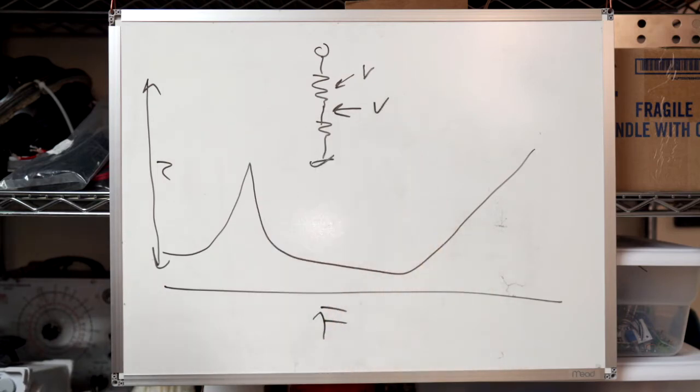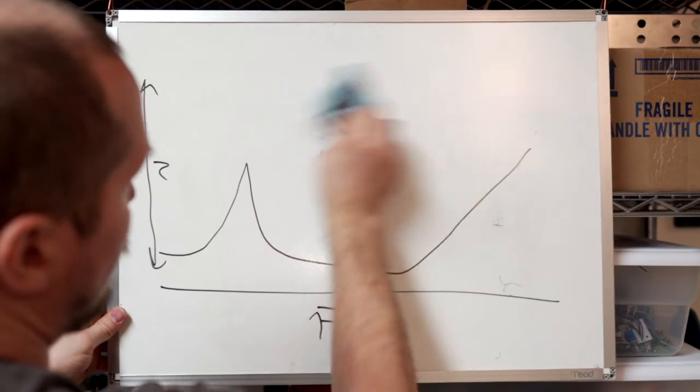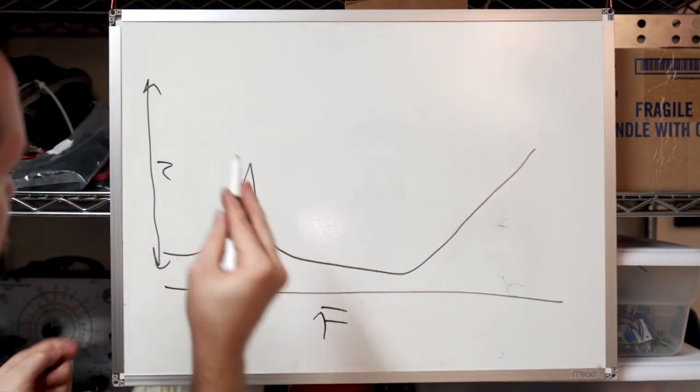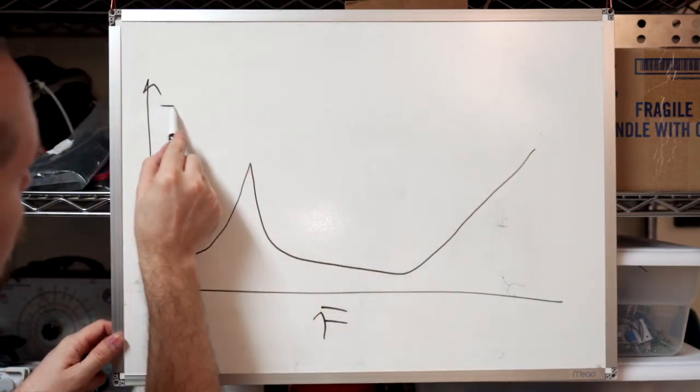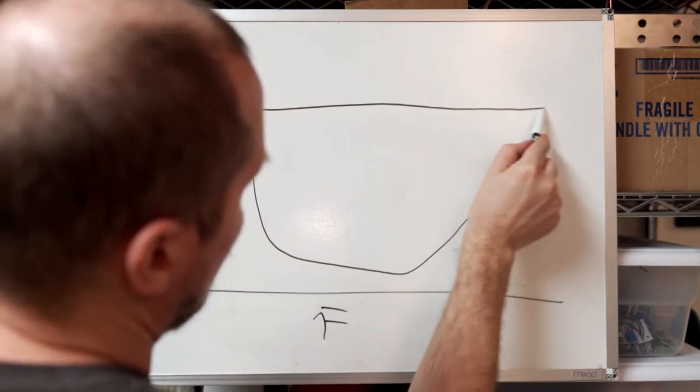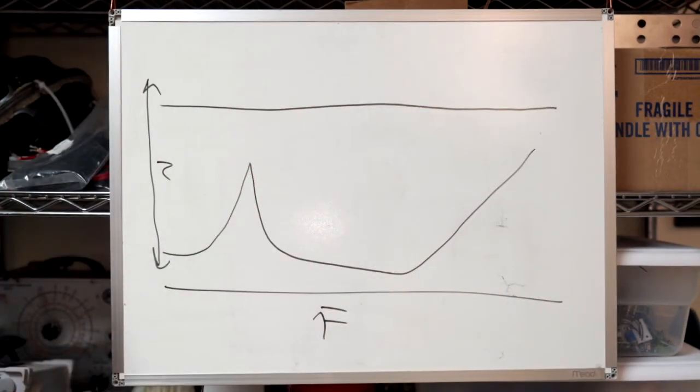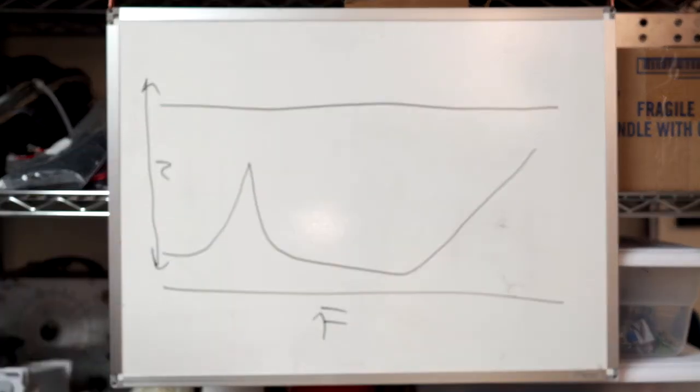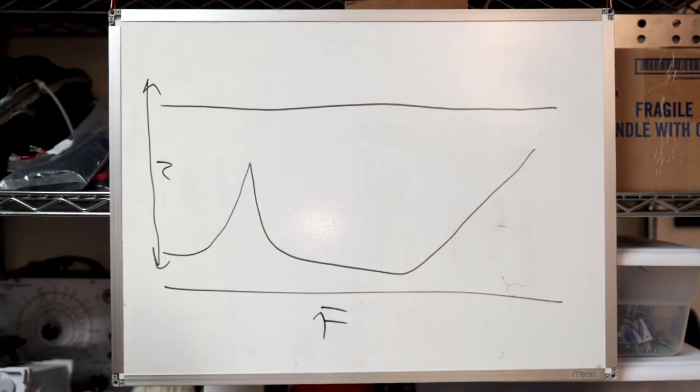This is important because when people are designing a loudspeaker, they're assuming a voltage source. They're looking for a frequency response that's flat, like this. We want a flat frequency response for our speaker, but this is only generally the case with a very low output impedance amplifier.